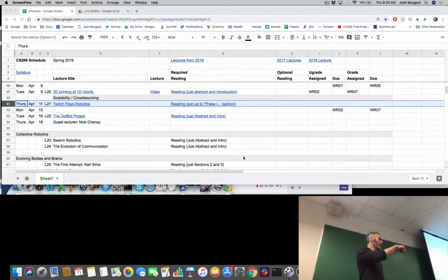So if we evaluate the same controller just twice in 2 random environments, it's possible that a bad controller gets lucky or a good controller gets unlucky. And we can rule that out by evaluating the same controller many, many times, but that's computationally inefficient. So a common technique is to use what's called frozen noise. What this means is that you're still going to have noise in your system. You're still going to be exposing controllers to random environments where the positions of the objects are maybe placed at random positions, or whatever else variation you're introducing into your environment. That's still different, but it's frozen in the sense that every controller experiences the same set of noisy environments.